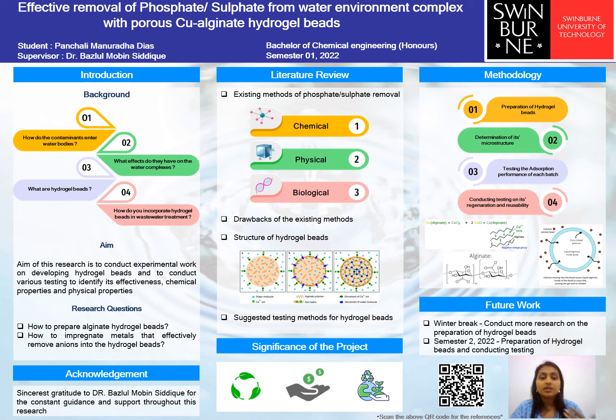The above discussed technologies all have the potential of removing sulfates and phosphate in good percentage values. Removing 75% of the above phosphate and sulfate is essential in the attempt to avoid water pollution globally. According to the Health and Safety Regulations Authority in the US, the globally accepted concentrations for phosphate and sulfate in effluent wastewater stand at 0.05 milligram per liter and 500 milligram per liter respectively. The only exception is in running water bodies, where the phosphate concentration is up to about 0.1 milligram per liter.